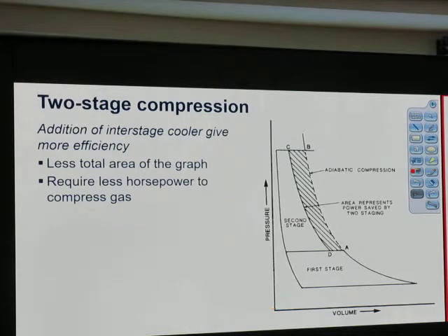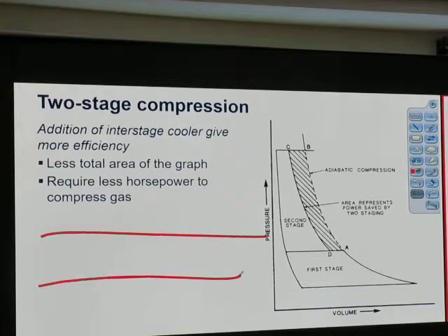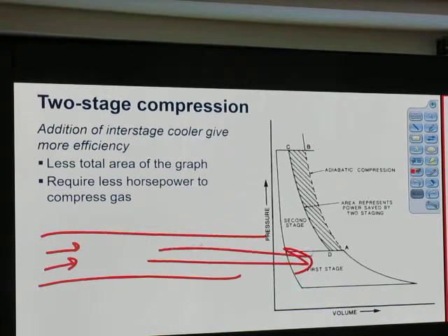But if the expansion is quick, like this, there's a detachment of the flow from the boundary, and it has edges over here. So we actually have pressure drop if the expansion is not that slow. So we flow slow and later on we flow quick like that. That will be accelerational pressure loss, because of the expansion.